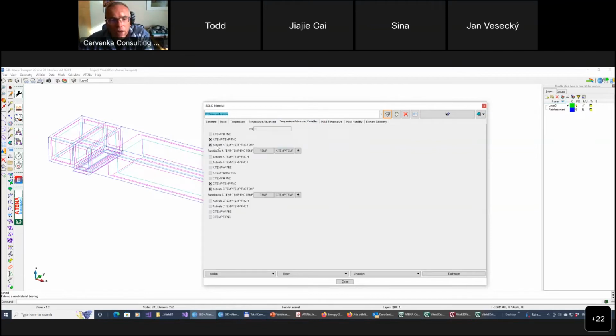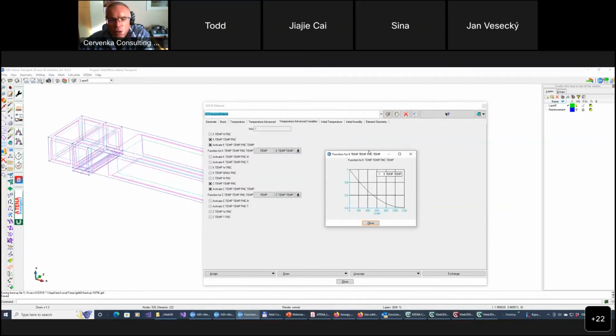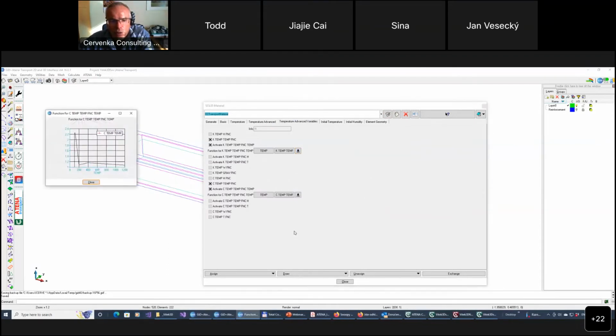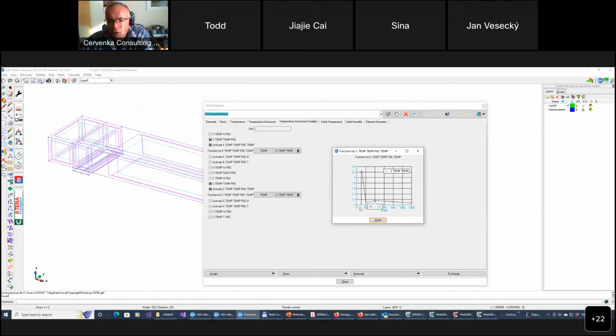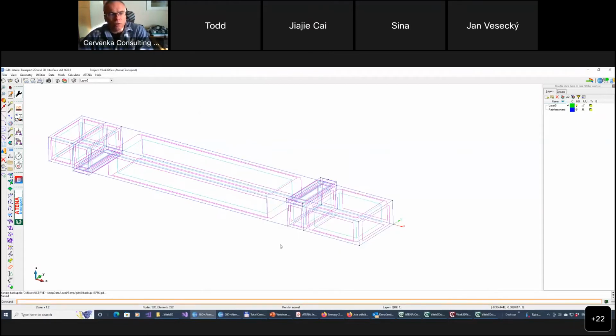What is important is this temperature dependency. So it creates these functions for the K. You remember I told you about, that's the conductivity, which is reducing. Or we select this dependency of the capacity, thermal capacity, depending on the temperature. So we define these parts in our model.